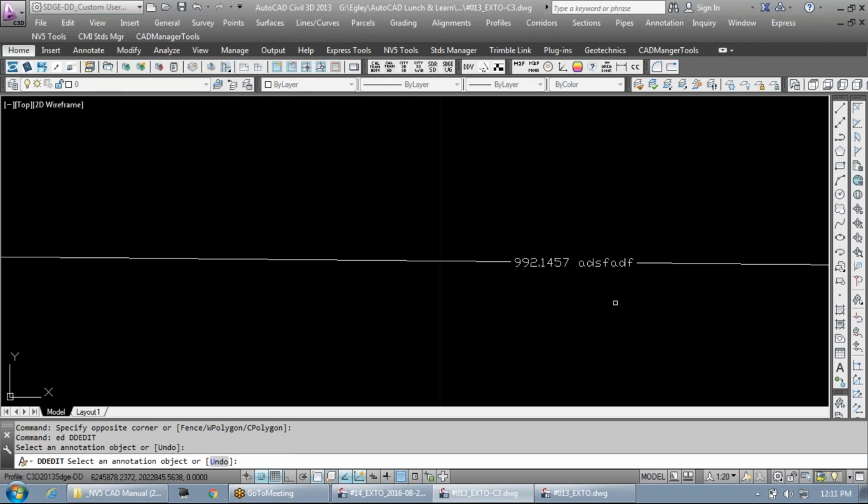We discussed line types a little bit. The innovation there was we have short line type definitions now. So if you're doing little laterals that are only, let's say, 2 inches long in your plan view, right? And your line type has, let's say, sewer. It has the S every 4 inches. It's not going to show on that lateral, right? So there's now a short line type that displays it every 2 inches or 1.5 inches, I forget. So those are now available for you guys to use for those cases where you have short little segments of lines and you need the line type to show.